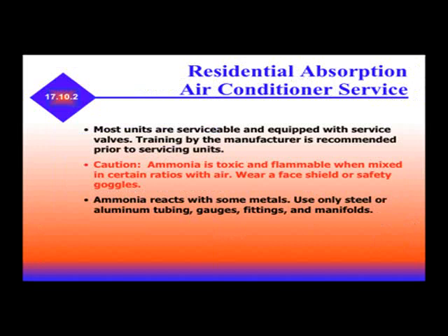You have to be aware ammonia is toxic and flammable when mixed with certain ratios of air. Wear a face shield and safety goggles. Ammonia reacts with some metals. Use only steel or aluminum tubing, gauges, fittings, and manifolds.